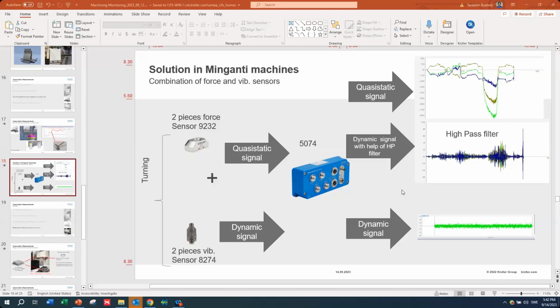Okay, just one more popped in. I'm curious if the machine tool builders have experienced issues with loss of stiffness in the machine by integrating these sensors into joints and tool holders, as we have seen today. No, but again, it also depends how you're doing it, right? Of course, if you are integrating in a way that the whole machine construction is being changed, then there will be a stiffness change, both dynamic and static.